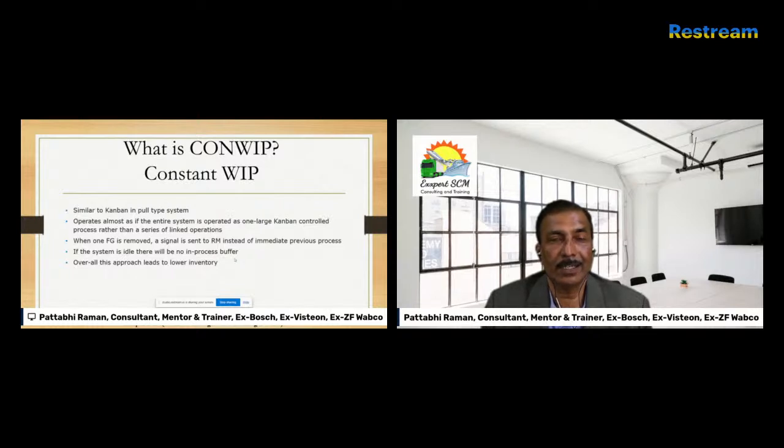In the regular traditional lean system, what happens? Assume there are 10 stations available, and in the sixth or seventh station, if something goes wrong, then it will stop there, and the entire operation will stop. None of the movement will take place. Traditionally it will not be able to pull the material from other stations, but here the material will flow till the station where there is a problem. So there is some minimization of WIP accumulation. Once the process problem is resolved, it will move through.